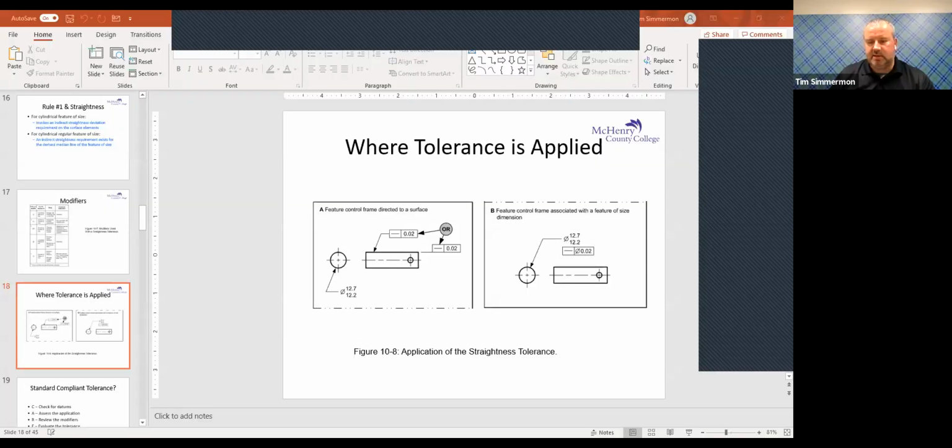But if we have GD&T on there, sometimes we're doing ourselves a disservice, and we have to hold those surfaces or tolerances considerably tighter to each other. So it's something that we're working with people on to help them understand what that bonus tolerance does, but it's not an easy concept to get.